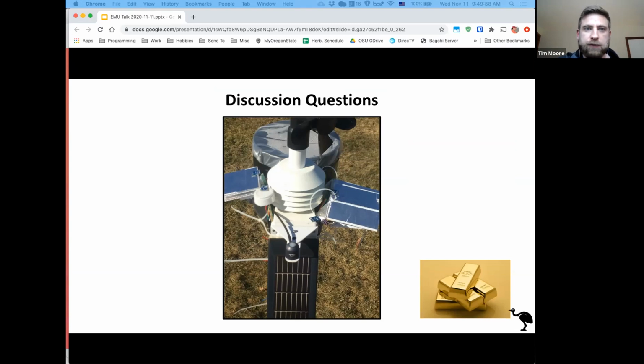temperature? This is in contrast, for example, to something like humidity, where the gold standard can be, we can actually get different measures of humidity because we have different salts that saturate solutions at different humidities. And so if we put our sensors over different solution types, we can see how accurately they measure humidity. But really temperature is a real challenge because of the lack of a gold standard that's going to allow you to account for any potential non-linearity in changes in temperature.